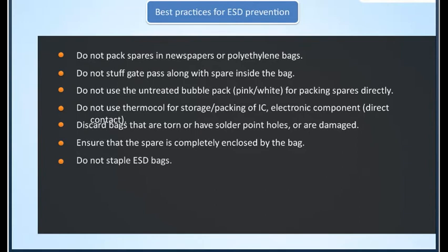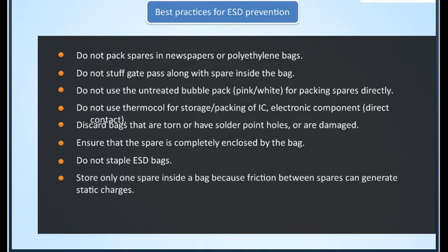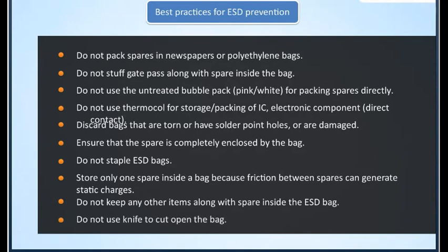Do not staple ESD bags. Number 8. Store only one spare inside a bag because friction between spares can generate static charges. Number 9. Do not keep any other items along with the spare inside the ESD bag. And number 10. Do not use a knife to cut open the bag.